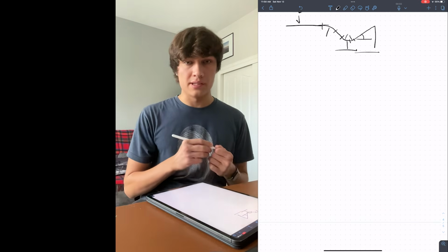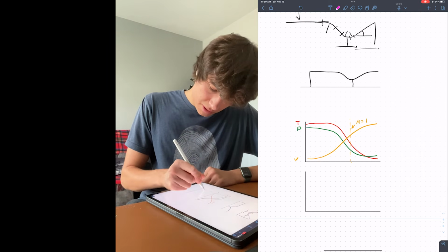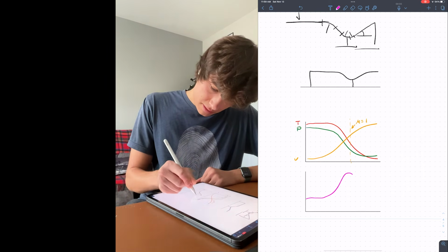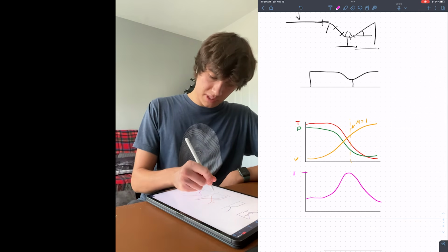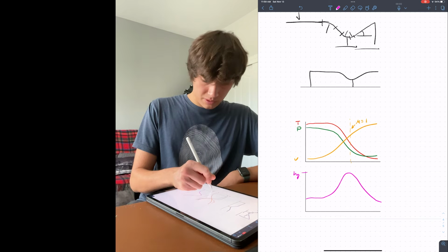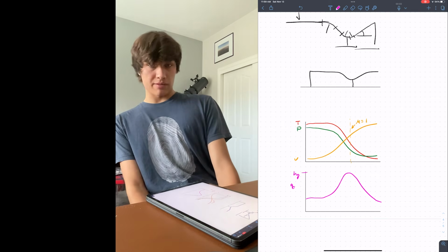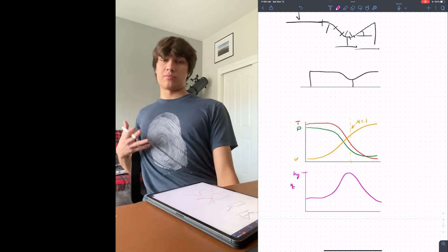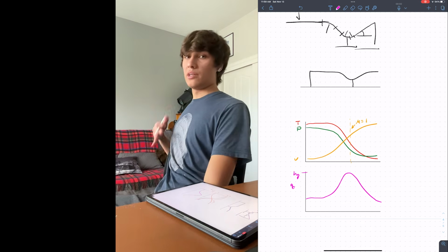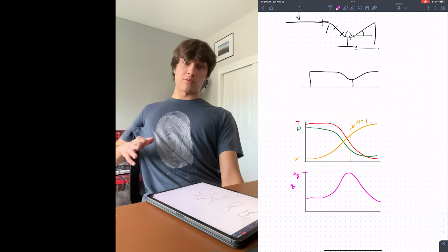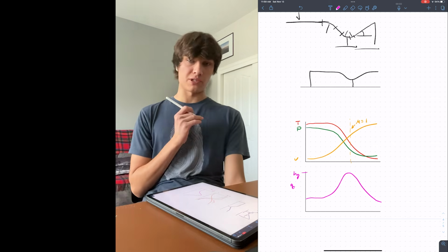One last parting remark is how heat transfer varies throughout the engine. So the heat flux in the rocket engine will roughly look something like this, with the nozzle experiencing the worst heating by far. This is HG and actually just total Q. The boundary layer heat transfer physics are kind of complicated. However, we can estimate the rough heat transfer using something called the Bartz approximation, which is an empirically derived equation that has been used in the industry for sizing, not necessarily for final design. I'm putting it up on the screen now.